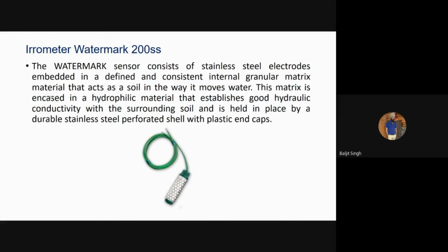That means this material is acting as a dummy soil, just in the way that water moves from this material. When this part of the sensor is dipped inside the soil, if the soil around this material is wet, the water will be transferred to this white portion, and according to the moisture of this material, the resistance of the sensor placed inside it will change.